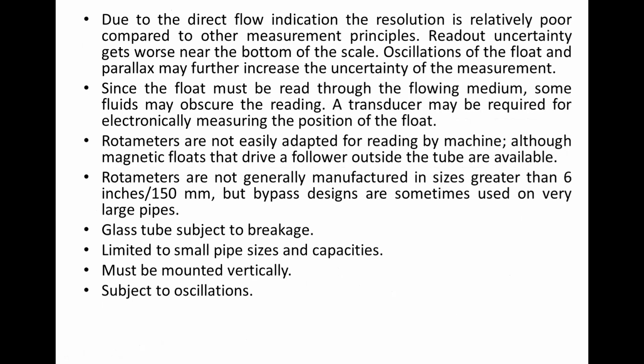Because of the direct flow indication here, resolution is relatively less compared to other measurement principles. Readout may be uncertain near the bottom of the scale. Oscillations of the float and parallax errors may also be involved. The float must be read through the flowing medium, and some fluids may obscure the reading. Sometimes a transducer may be needed for electronically measuring the position of the float, and they are not easily adapted for reading by machine.